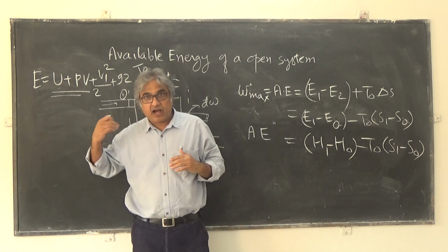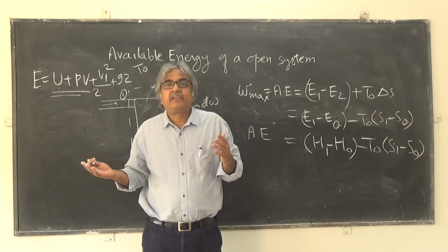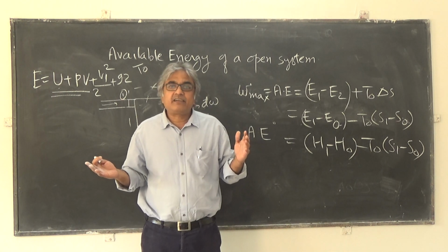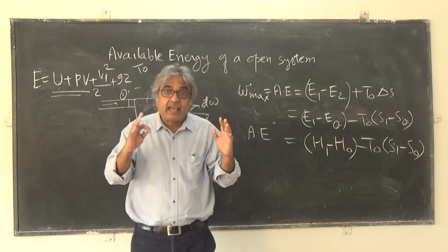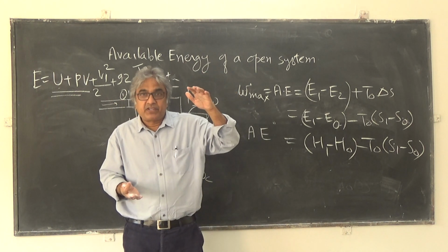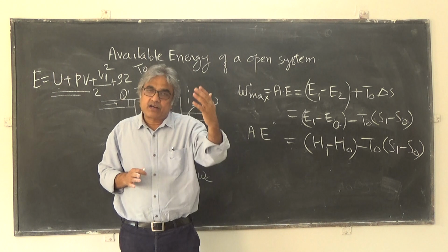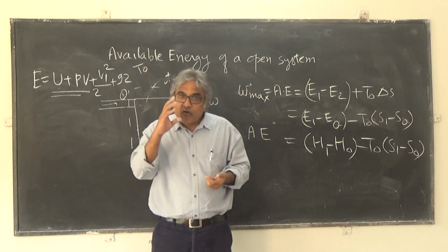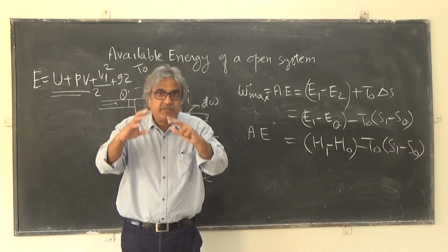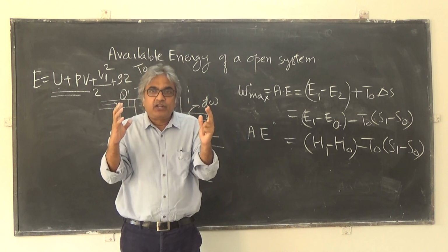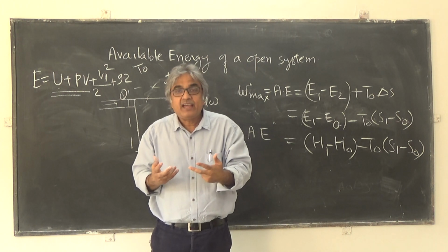And heat is given out at the condenser. So when the heat is rejected, that temperature at the condenser we will consider as the sink temperature. And then we'll find out the efficiency, T1 minus T2 by T1. So we are considering a Carnot engine running between the same temperature limits, and we find out its efficiency. Our actual efficiency, as I told you, is work upon heat. Now it must be obvious to you that the efficiency of the Carnot engine will be highest. So we'll compare the actual efficiency with that of the Carnot engine efficiency. Okay, and we write that ratio.